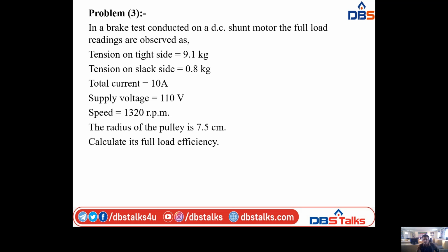Here the armature resistance for both the motor and generator is 0.4 ohms, and calculate the efficiency of each machine at this load. Here they given the field test on two mechanically coupled similar motors with their fields connected in series, with one machine running as motor and the other as a generator. So here the connections and various voltages and currents are shown in figure. So this is the diagrammatic representation of the field test connected on motor generator set.